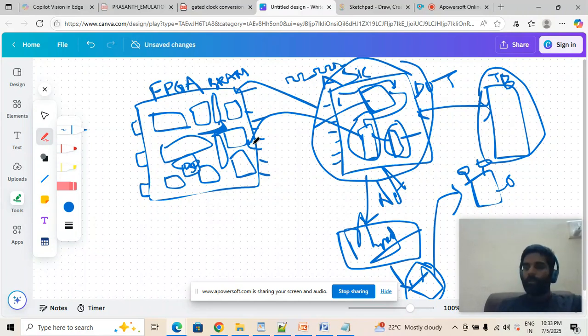Before we say I want to put my code into my FPGA, it's not going to be taken directly as it is. We have to provide all this information to the tool, and then you have to map your RTL into FPGA. At the same time, changing the RTL is not a feasible way. If you start changing your ASIC RTL because you want to map into FPGA, just imagine, again you have to go back to your ASIC only. So you'll be keeping two RTLs in your hands, and it's not a feasible way of doing it.